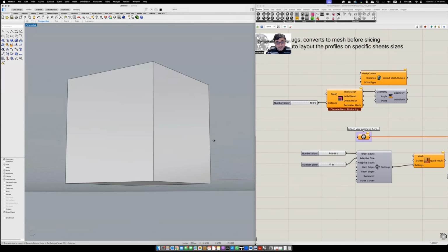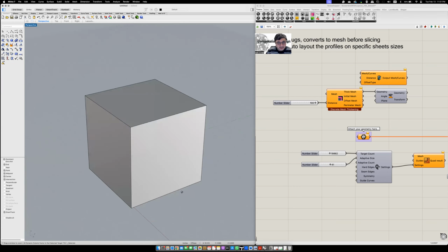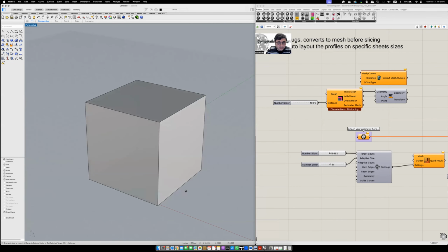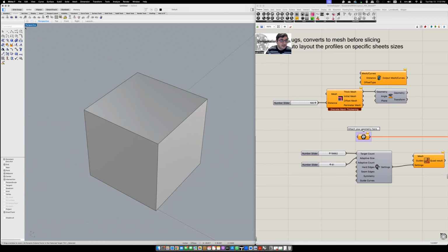Get this object. This is the hill. So what we can do with this box, I mean, you can go from pieces to whole or from whole to pieces, following the architectural style that we covered in the lecture, mass and volume architecture. Let's start carving this. Maybe I will carve a ramp here, right? How do I do that? So I go to C-planes, take my C-plane to this surface. That means that I'm going to sketch here something that will identify my ramp.